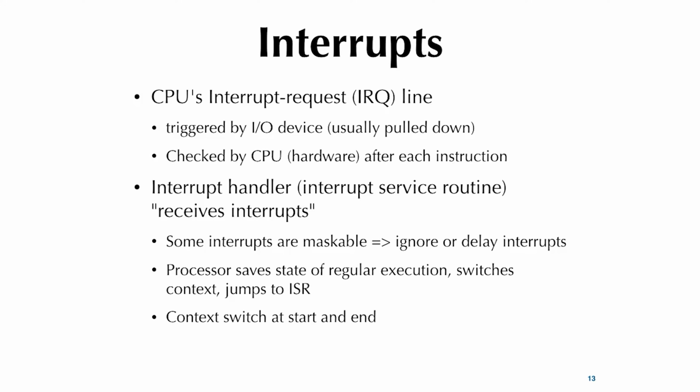That's called interrupt chaining. And so that means the IRQ line itself is a bus. It's a special kind of bus. It's a 1-bit bus, okay? But how do you then resolve these different requests? Some device may say, I'm ready, I'm going to assert the IRQ line. The other devices say, I'm not ready, I'm not going to assert the line. So what happens? Well, that's why you need this pull-up structure.